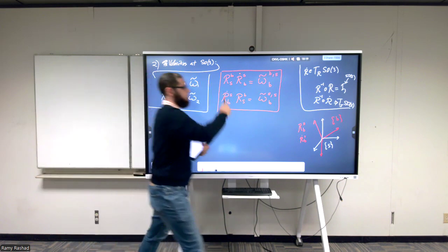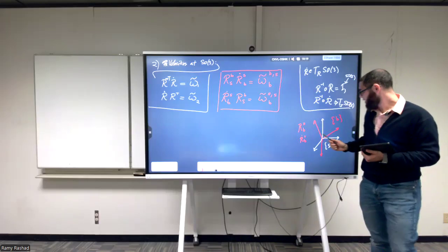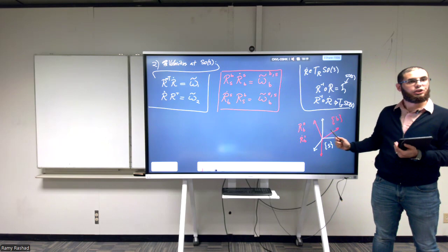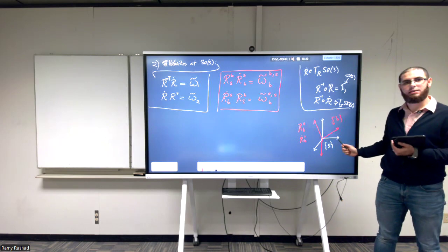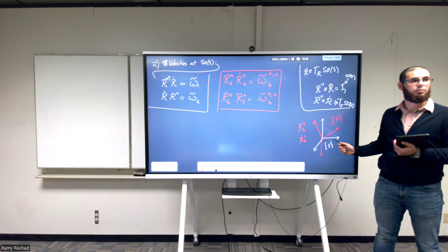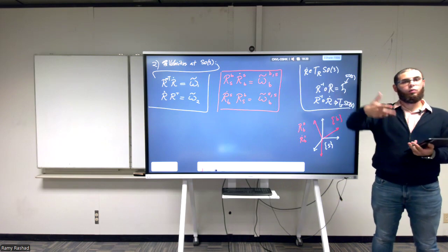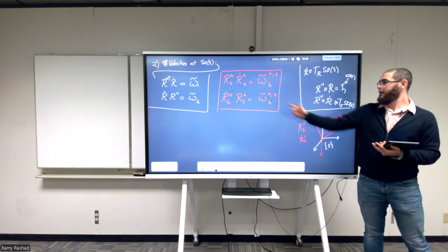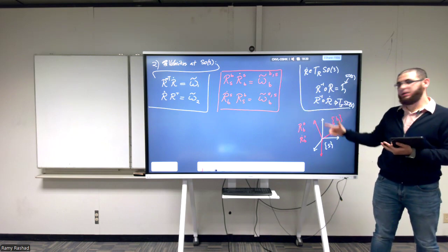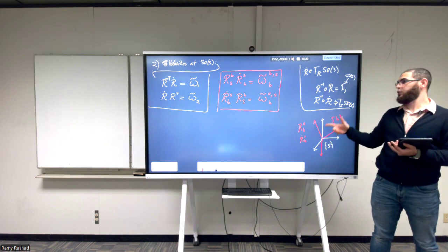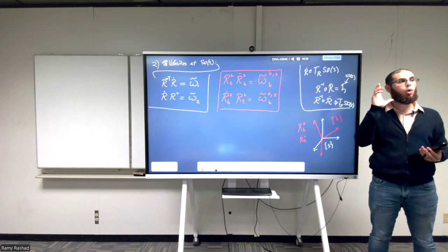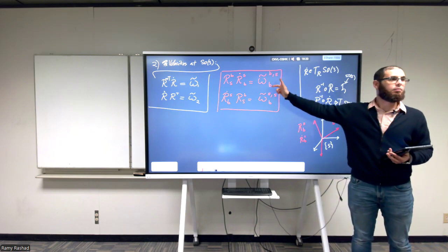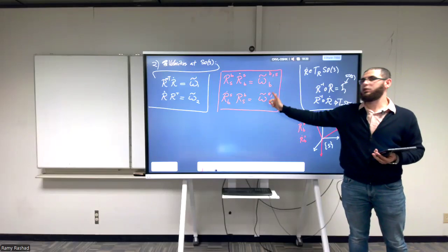The first one, you can read it as follows. It is the angular velocity of frame B changing with respect to frame S expressed in the frame B, which is the moving one. The second one is the angular velocity of frame B with respect to frame S. So it's the same motion. This is important. When these two are the same, we're talking about the same thing, the same motion. But the numbers, of course, are different, right?